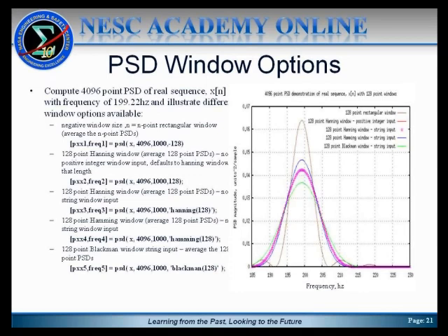And again, you see I've provided in the input sequence to each of those PSD functions also the non-default input for 4096 points. I want the PSDs each to be at 4096 points. I've told it the sample rate was 1000 hertz. So then again, the frequencies that come back are in hertz now, not normalized frequency. And you can see what you get out of it.